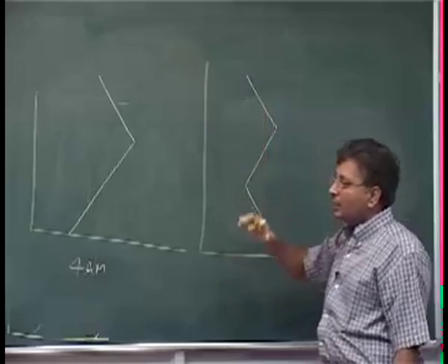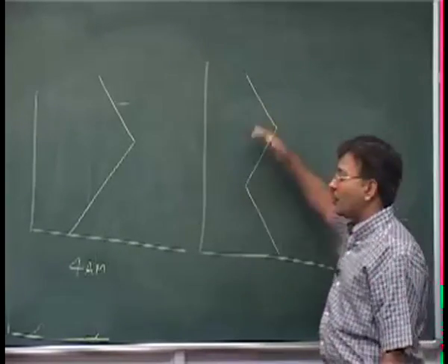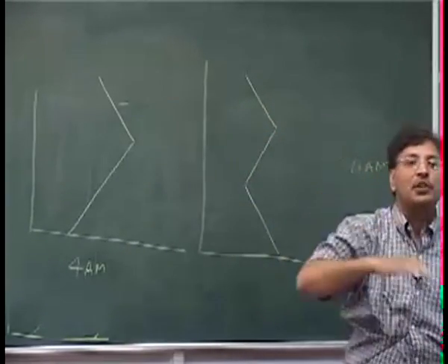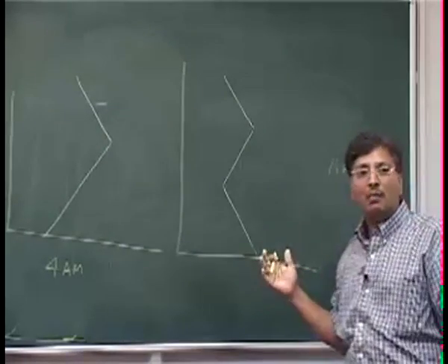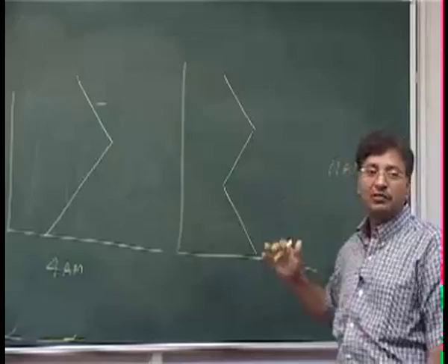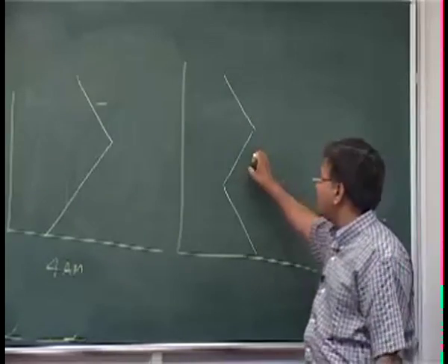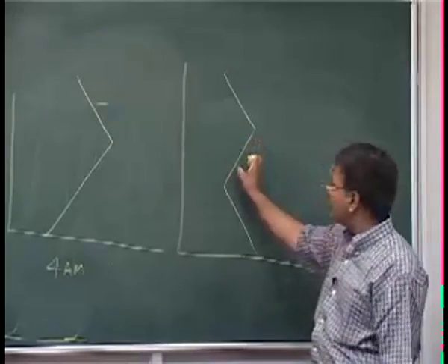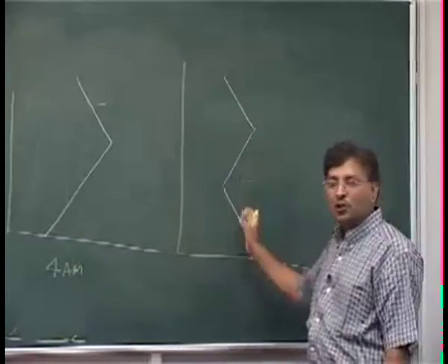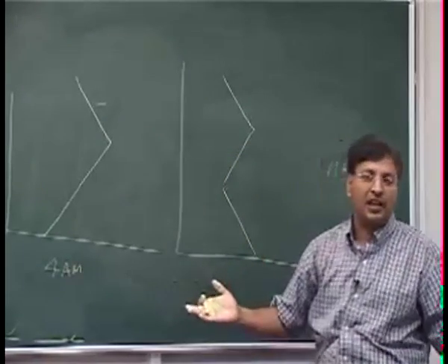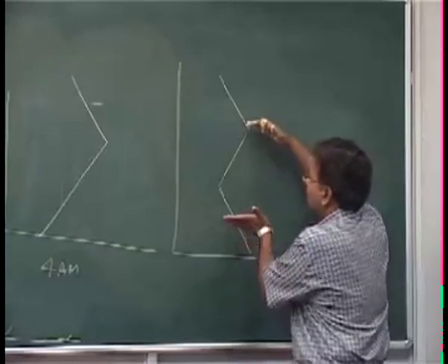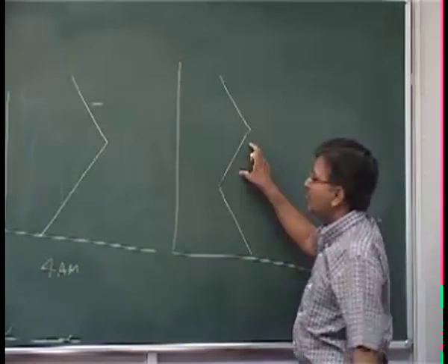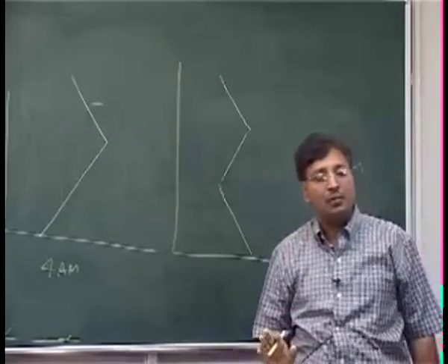And depending on this layer going up and down, the dispersion of your chimney will vary or change. And that is what we want to somehow model, as to how these variations will be there. So sometimes your chimney may not disperse, because if your chimney is sitting here, you will say, oh sir, this is a bright day, sunshine, and we see the chimney is not dispersing, because your stack is trapped in this one, and here the dispersion will be very, very poor.